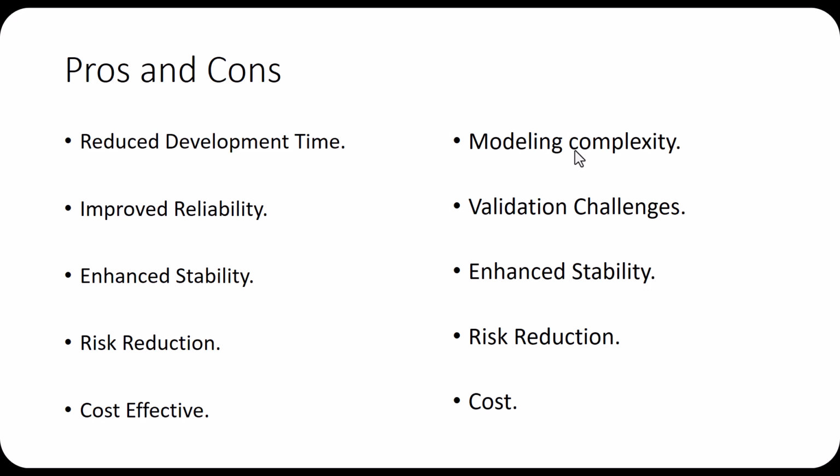And risk reduction. Enhanced stability is a typo, please ignore that. Risk reduction, though we say it is a pro, is also a con, in the sense that when you simulate, I told you there is no way you can burn an RPI, no way you can burn a resistor or an LED. So you don't care about any precautionary methods like putting load resistors or connectivity or fan-in fan-out capabilities of the hardware. But in real time, all those things matter. So though that advantage is there, that is also a disadvantage in simulation driven.